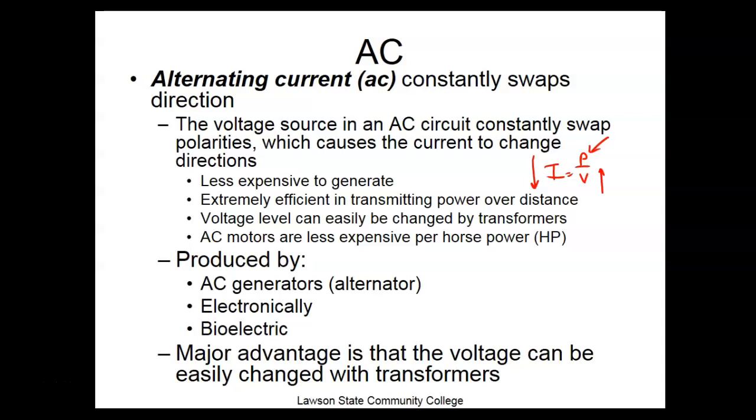So what we do is, the closer we get to you, we start stepping that voltage down. As we step the voltage down, the current to deliver the power goes up, so the conductors have to be bigger. This is why you have two voltages at your house. The two voltages we have are 120 volts AC, and 240.